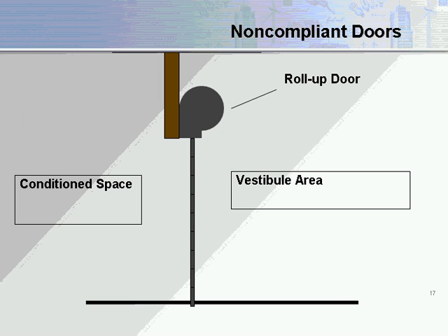We're bringing up some of the owner-builder stores like the Lowe's and Home Depots. Again, from a material handling standpoint, this is where you may be able to exempt some of those doors if they're using a roll-up door for material handling and that type of thing. Because again, you're bringing lumber and things like that through the doors, and a vestibule would actually get in your way in that scenario. And those doors would typically be open quite a bit of the time anyway. So you could probably exempt a lot of those doors if they're roll-up doors, but you do need to take it case by case.